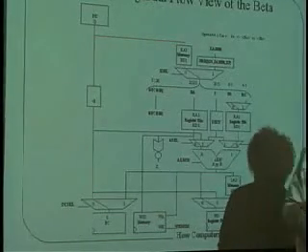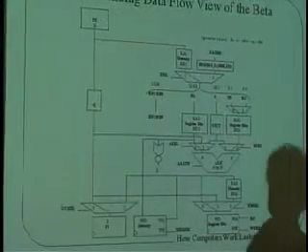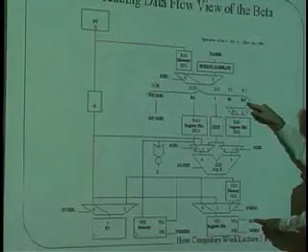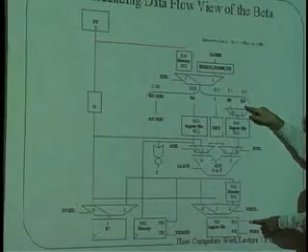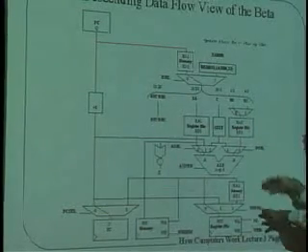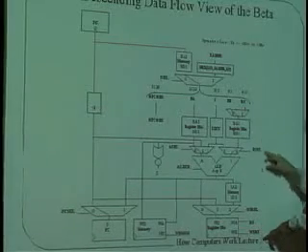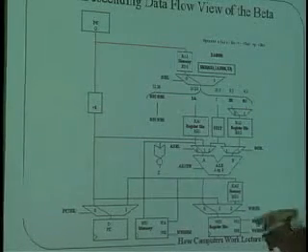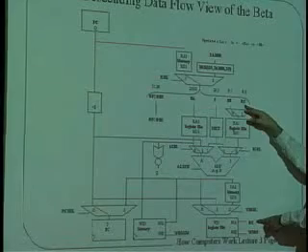So the connection between RC up in the kind of middle and the RC down in the lower is these are exactly the same. It is not drawn. What I could have done is I could have drawn a wire that came down here, but it kind of would have messed things up. And maybe the next time that I do this, I'll draw a wire here. These are the same. If you see two things and the letters are the same, then they are the same.